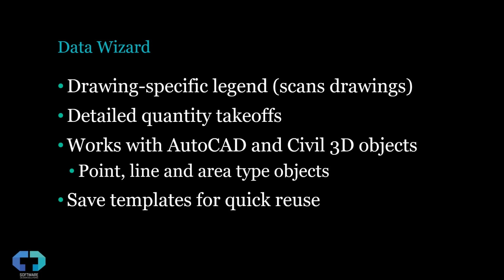You can save templates out of Data Wizard for quick reuse. So this might be, you define how an existing conditions sheet legend would look. You can save all those settings and then distribute it to end users, and they can just load this and generate tables in a matter of seconds.